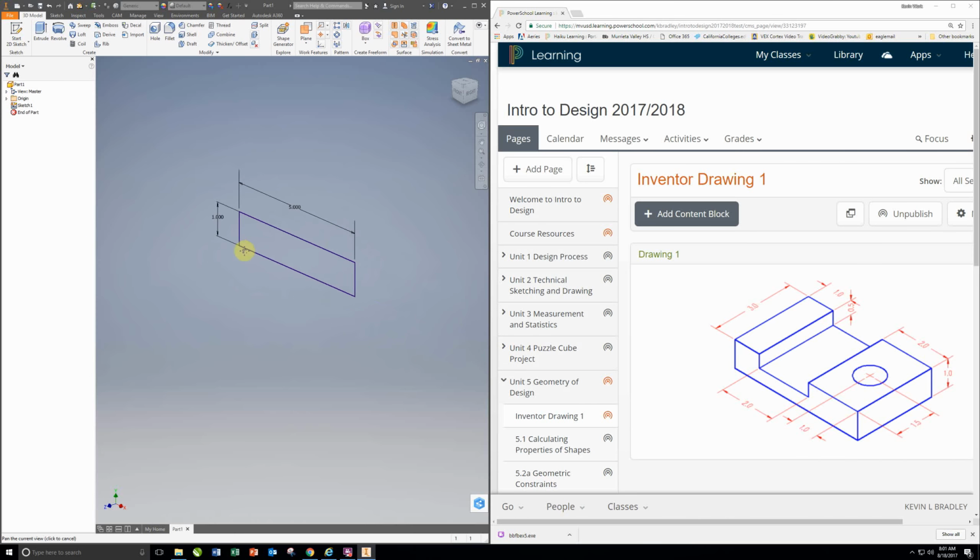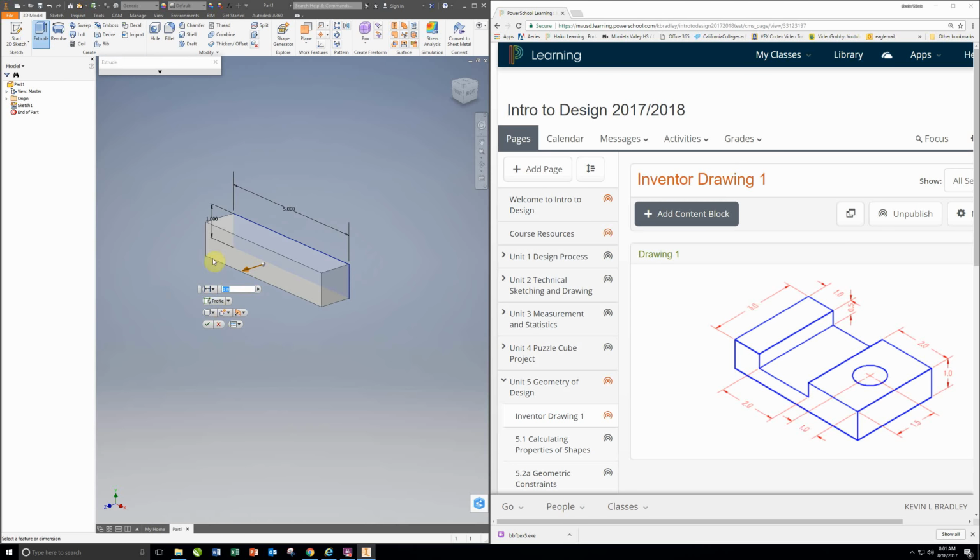So there's that. And now we get to the 3D parts. Okay, we are actually going to extrude this a distance of 3 inches. So we're going to use Extrude. Okay, this is kind of like the shortcut bar. I always like this guy up here because this is how I learned. This didn't used to be here in the old versions. So I always use this guy up here. But we want to extrude this a distance of 3 inches.